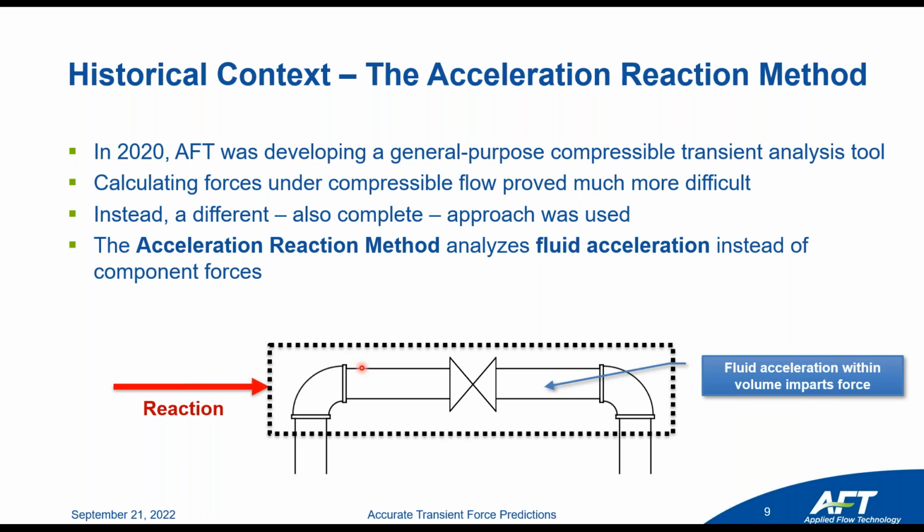Now that we have two methods, we want to give it a name, and we have named this the acceleration reaction method. Because of the way that you draw the control volume, you can actually ignore all the pressures. It's kind of nice because they exist, but they all cancel out. The only thing that doesn't cancel out are these acceleration terms. And I'm going to let Scott dive into this, but essentially we're going to look at the fluid acceleration within the control volume, and that imparts a force.